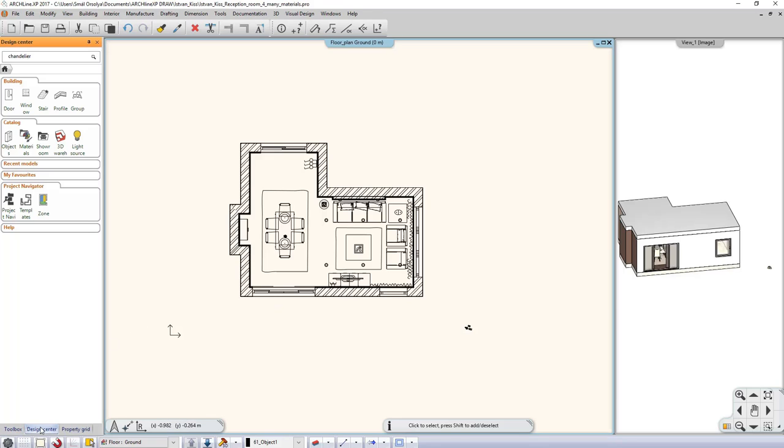From the 3D warehouse, download objects which are too large and contain too many materials. These objects can greatly slow down the operation of the program, since they are often larger than the plan itself. The program warns us in the following 3 cases. When the object is too large, so it contains more than 50,000 polygons. When the object contains more than 50 materials, or when the physical extension is larger than 100 meters.